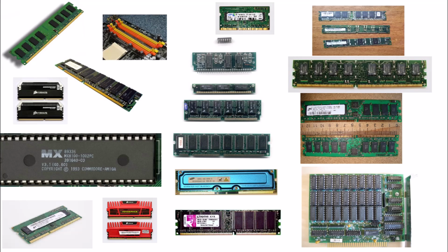In DDR/SDRAM, data is transferred on both the rising and falling edges of the clock, resulting in twice the bandwidth. The dice are powered by 2.5 V, which, together with a reduction in internal memory capacitance, results in a significant reduction in power consumption. Access time to data in RAM in the latest DDR/SDRAM is approximately 4 ns.